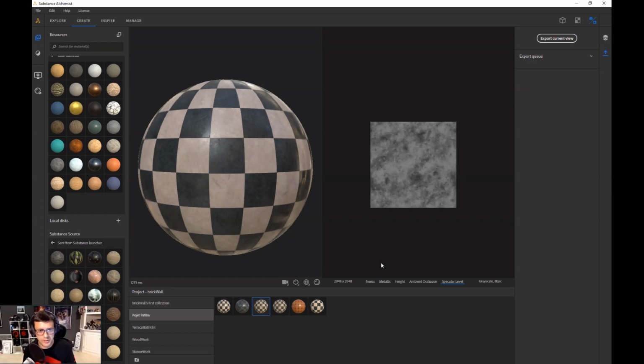Wow, that's awesome. Simple enough. Another thing I can mention is that you could use the Substance archive file, the SBSAR, because we have an integration within 3ds Max that also works with various renderers, Corona being one of them. You could drag and drop the SBSAR into the node editor, run the renderer template, and boom, it creates the material for you.